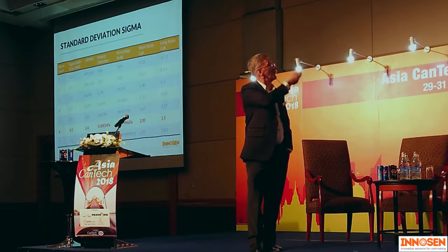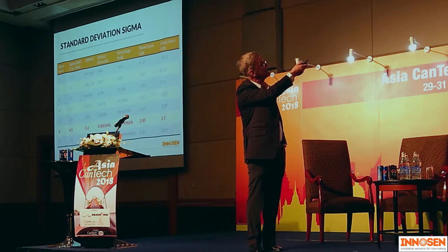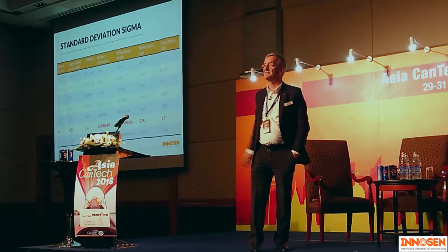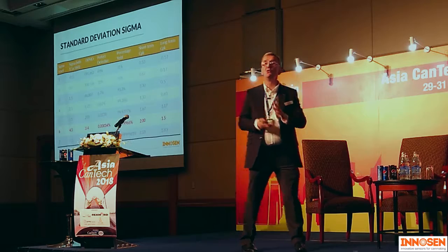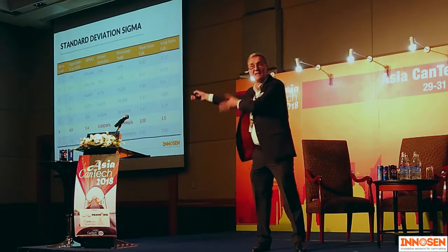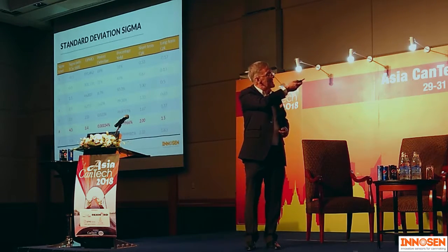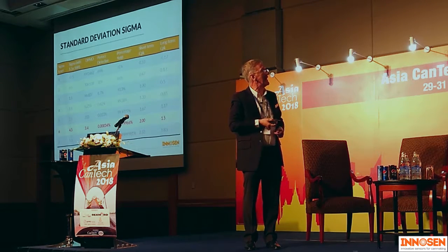Now, that gives you the possibility to go further, and you then get a table like this. You go plus or minus 1 standard deviation, 2, 3, 4, 5, up to 6. Everybody's heard of Six Sigma. What is this Six Sigma? You now move 6 sigma that way, 6 sigma that way. And to compensate for the long-term stability of processes, you subtract plus or minus 1.5 sigma.